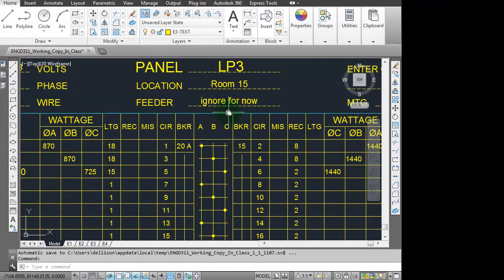So we're going to do that using the information sheets that I gave to you guys for doing your motor schedule calculations. So that's going to be from table number 2, I believe. Is it table number 2? Just let me check. Yeah, table number 2. So if we look at table number 2, table number 2 gives us the ampacity of the conductor.